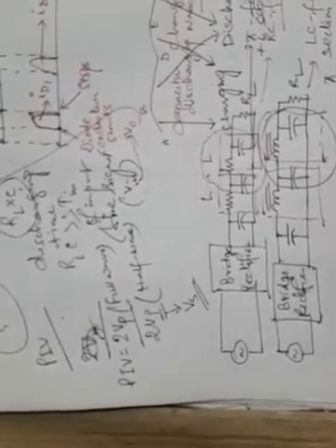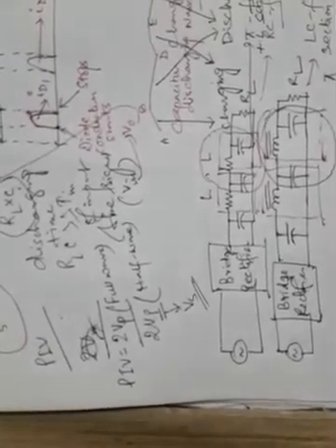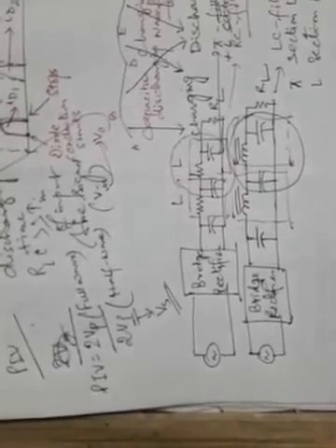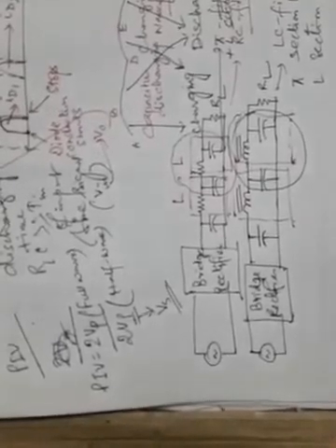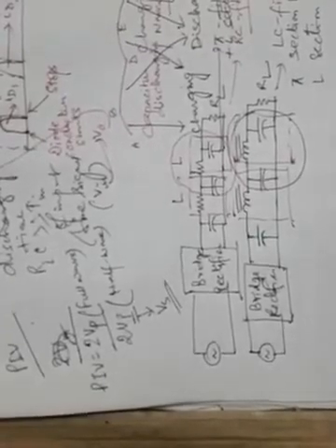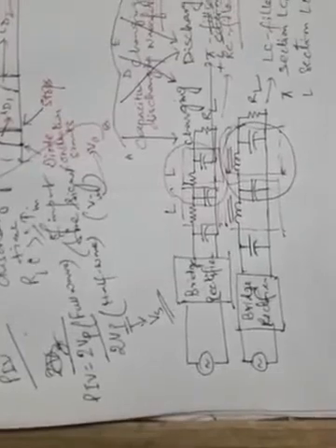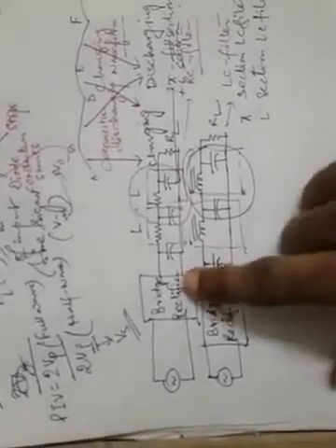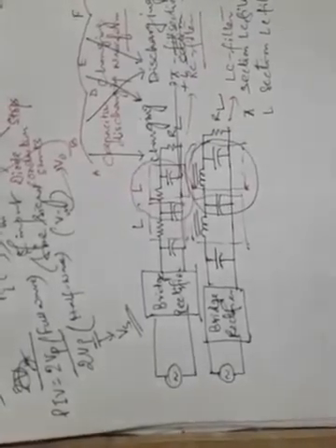Now, if we consider the RC filters, R, L, C are the passive components used for making passive filters, and they are often connected between the rectifier and the load resistance. But nowadays these passive filters are very rarely used in semiconductor power supplies, but in some special applications such as audio power amplifiers, you may see this configuration of RC filtering. And in the first diagram, the bridge rectifier with a capacitor input filter is initially shown, and along with that